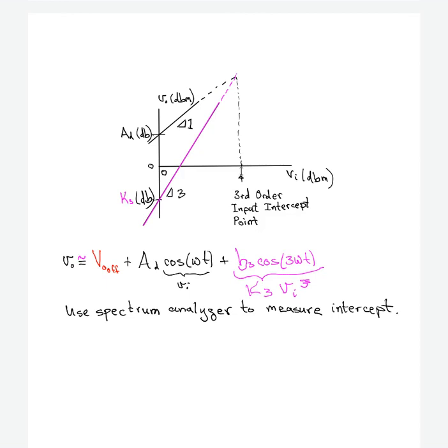So that gives you a little bit about the effects of distortion coming from the fact that the amplifier cannot output a voltage bigger than VCC or smaller than VEE. In the next video, we'll look at what happens much more carefully on the V output offset voltage and try and relate that to input parameters, which are usually specified in the op-amp manufacturer's data sheet.